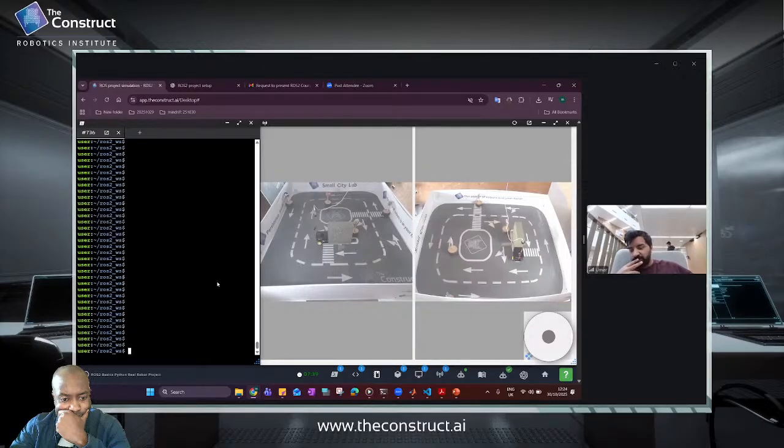We use an action because we wanted to start recording, we wanted to send feedback, and we wanted to ensure that when the robot reaches the initial position, the robot stops immediately. With topics, you cannot manage that whole sort of process, and topics are basically used only to stream data, and they cannot control when to begin or end. That is my understanding. Yeah, it's correct. It is very much true. So well done on that bit.